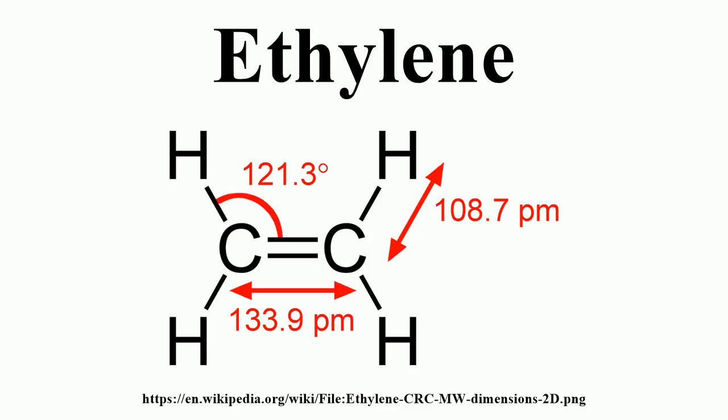To meet the ever-increasing demand for ethylene, sharp increases in production facilities are added globally, particularly in the Mideast and in China. Industrial process: ethylene is produced in the petrochemical industry by steam cracking. In this process, gaseous or light liquid hydrocarbons are heated to 750 to 950 degrees Celsius, inducing numerous free radical reactions followed by immediate quench to stop these reactions. This process converts large hydrocarbons into smaller ones and introduces unsaturation. Ethylene is separated from the resulting complex mixture by repeated compression and distillation.